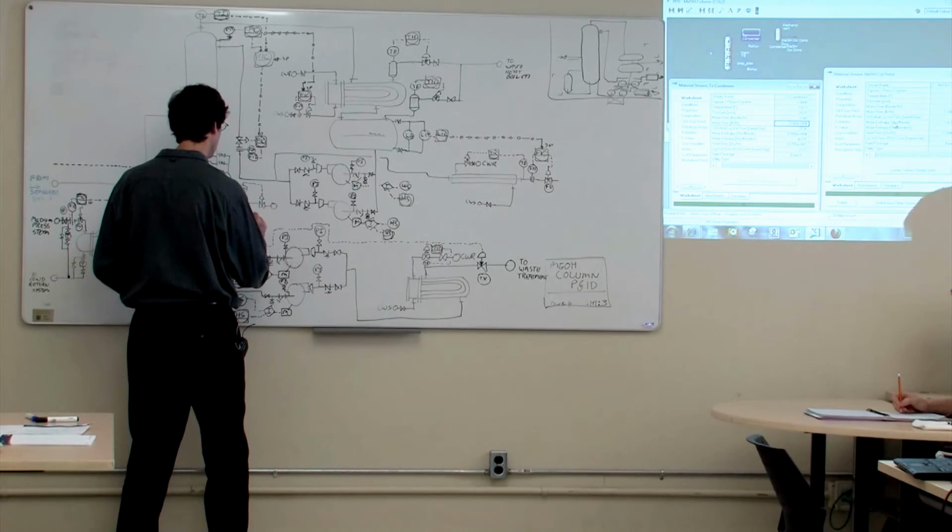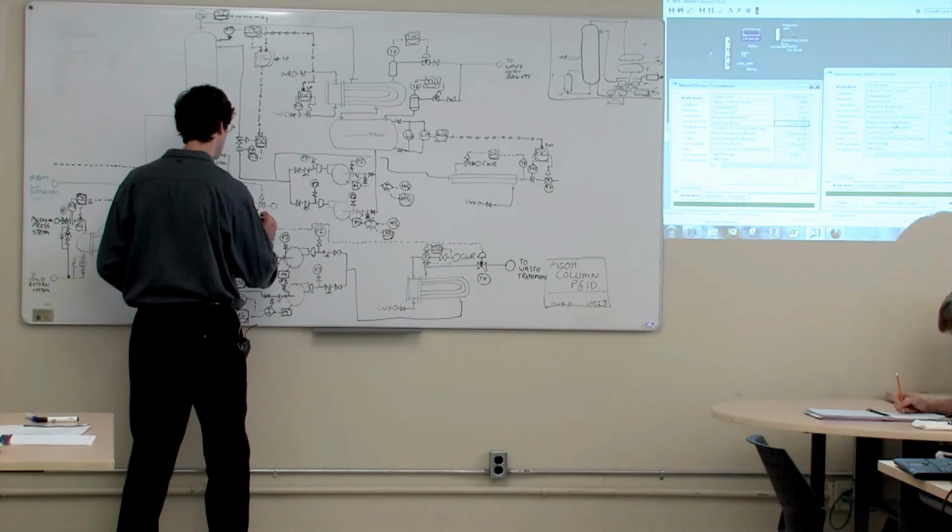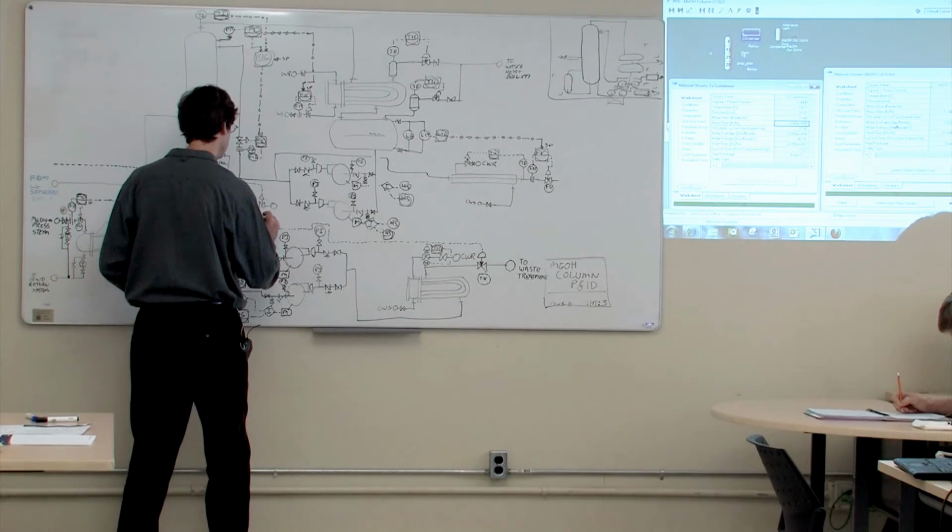Often just write sample cooler. You should make sure we've got a cooling water supply and a cooling water return from them. And that'll keep the operators fairly safe.